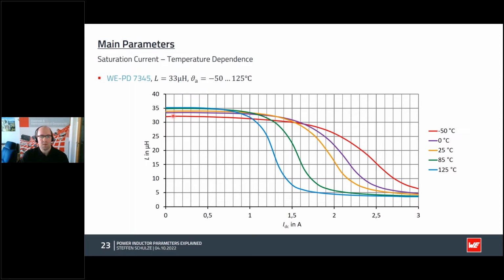The nominal value of the inductance rises with increasing temperature, but the more dramatic effect we see here: for higher temperatures, the saturation current is much lower.